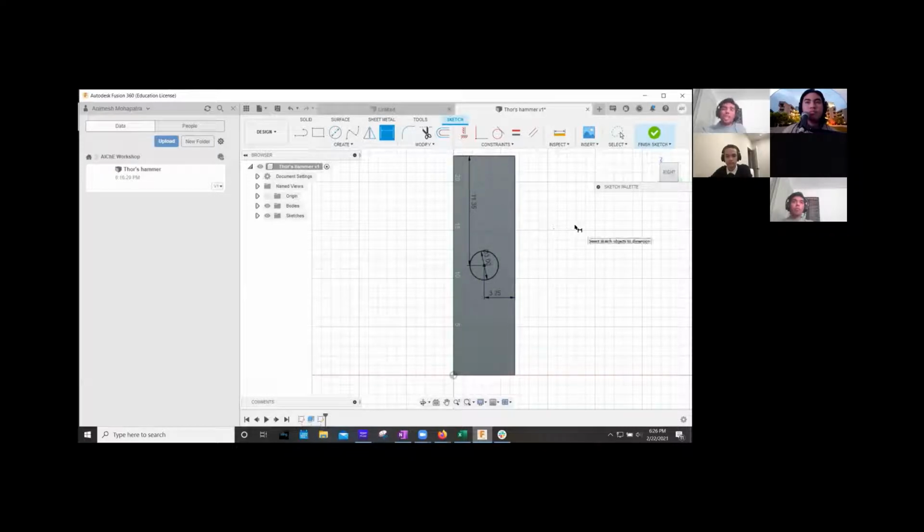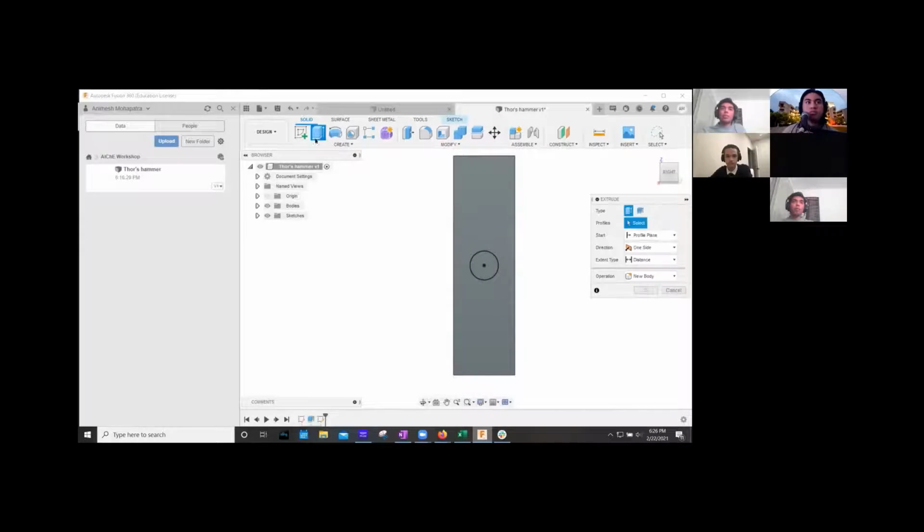But now we have to actually make it a hole, so we have to bore into it. So we're going to use the Extrude tool again, just in a different way. So we're going to click this, and instead of making the value positive, which would mean it would be coming out at us, we're going to make it a negative. And I'm just going to say that it's -1 because that makes life easier. So the depth of our hole is going to be 1 inch. That negative is just specifying that it's going away from you, right? And then -1, and then enter.